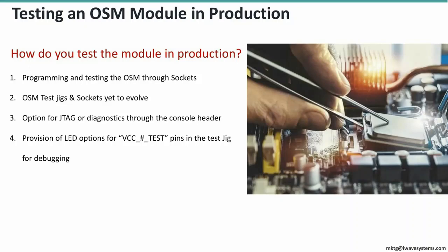So what we saw is, okay, most of the designs, correct, you can have a small header or a tapping point where you can bring pins and come into contact, and bring only the console on the module itself. It costs about 6 or 7 soldering joints on the top. So that's what we have tried to do. With that, we were actually very successful in terms of testing the complete module, though we cannot test all the pins in the bottom. But the module features, the CPU, RAM, power management, everything we were able to test through these small headers, just a test pin header.